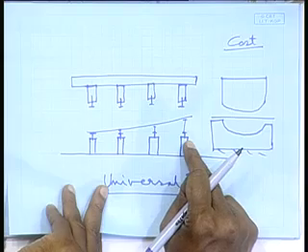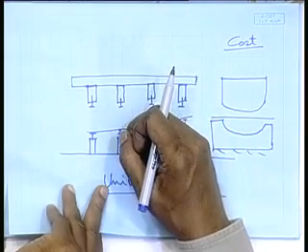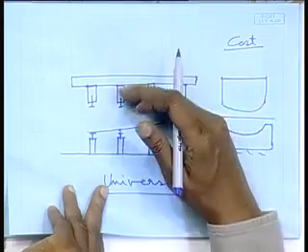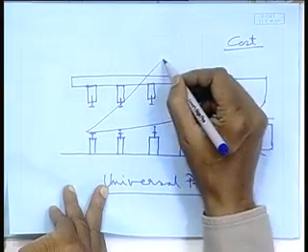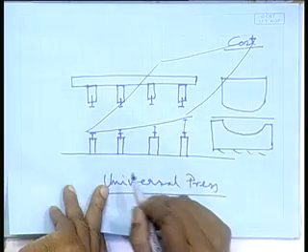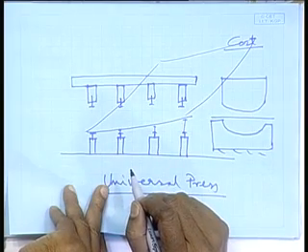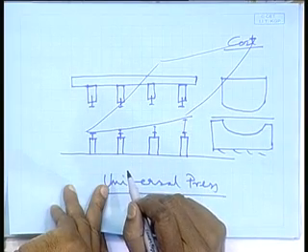With that springback, I add that springback allowance to the defined surface, right, and accordingly actuate my jacks, press it down, it bends, release it, and then this surface has to be checked for the coordinates, whether it has come correct or not.